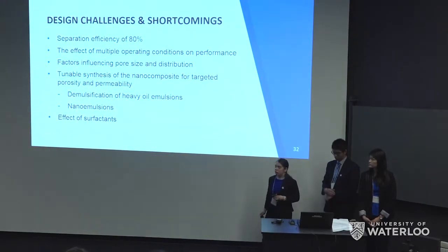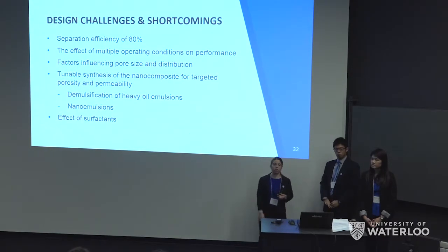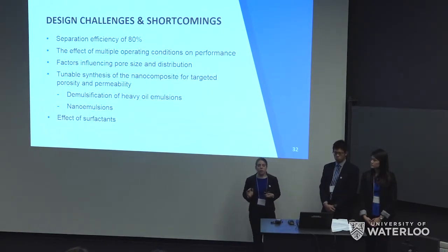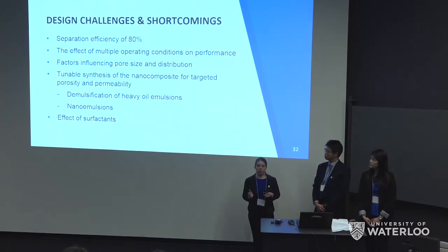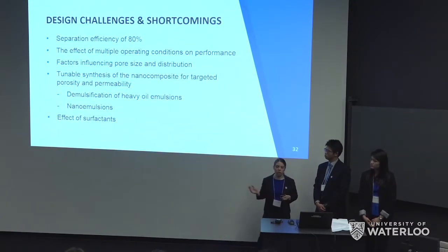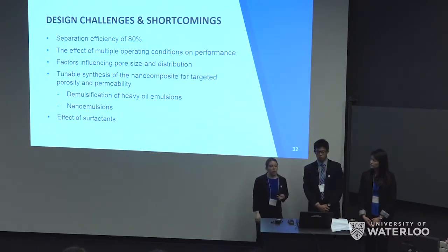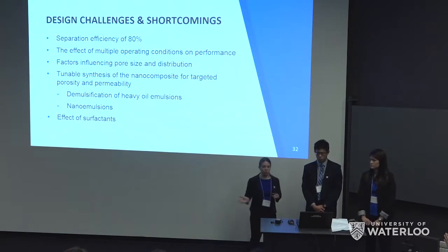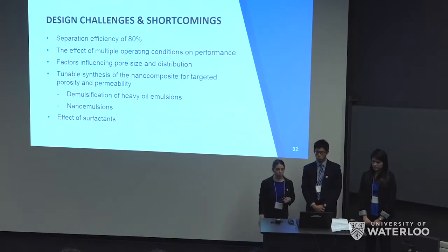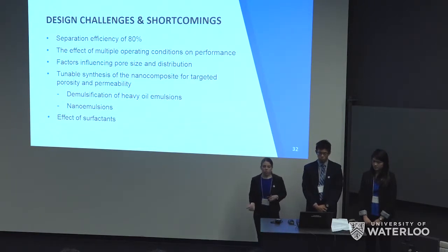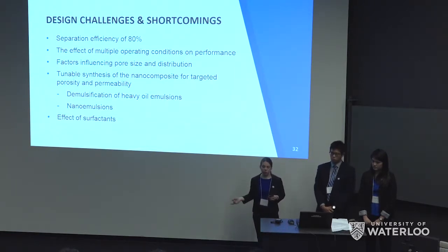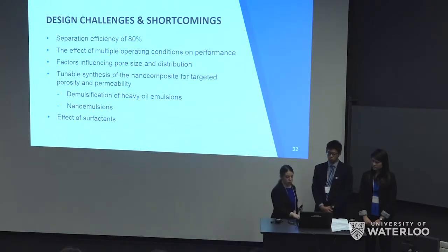So challenges and shortcomings with this, again, separation efficiency of 80%. We should also be testing many different conditions at the same time, so chemical, thermal, perhaps some applied pressure as well, all at once, see what that does. Also looking at factors that influence pore size and distribution, particularly because the viscosity of crude oil is a lot higher than in some other applications, so the pore size would need to be tuned based on the viscosity. Extending to nano-emulsions and, again, heavy oils and also surfactants.